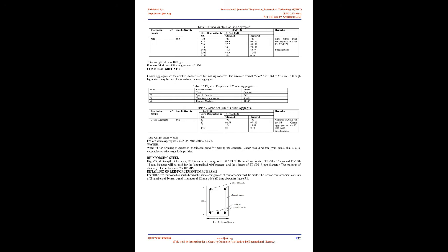Aramid is the short form for aromatic polyamide. Aramid fibers are most commonly known as Kevlar, Nomex, and Technora. Aramids are generally prepared by the reaction between an amine group and a carboxylic acid halide group. Commonly this occurs when an aromatic polyamide is spun from a liquid concentration of sulfuric acid into a crystallized fiber. Fibers are then spun into larger threads in order to weave into large ropes or woven fabrics, Fig.